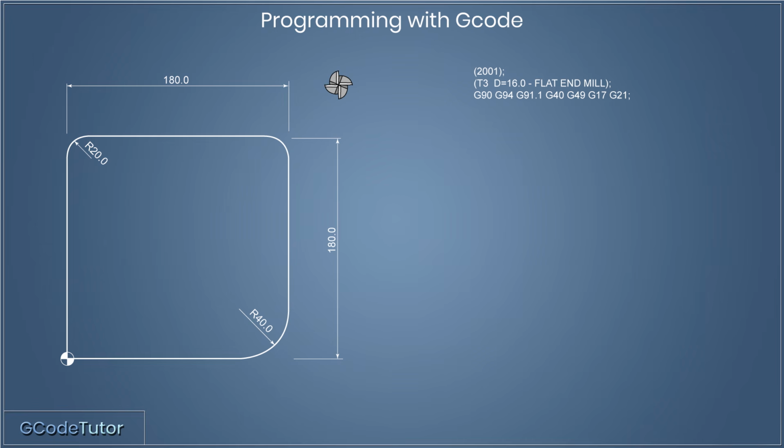Now depending on whether you prefer working in metric or imperial, this G code tells the machine which one we are using. G21 is the metric system and G20 would be the imperial system. So it reads any dimensions using whatever system we defined here. Now I tend to work in both imperial and metric, but on this program, we're going to work in metric to keep the numbers more readable and simple as we're going through the program. So I've decided to write this program in metric, so I'm using G21.